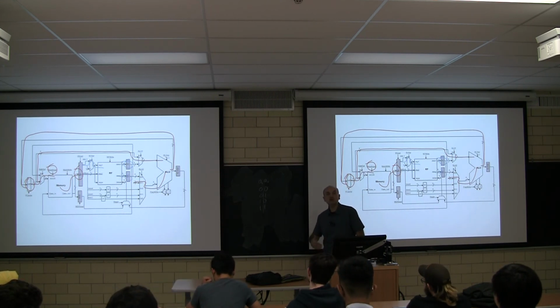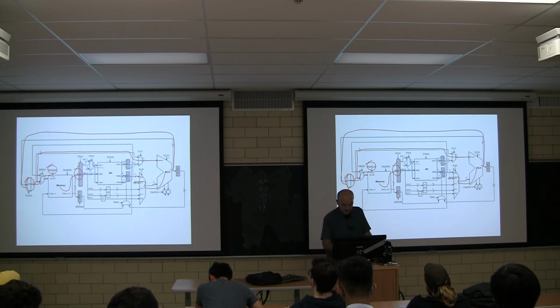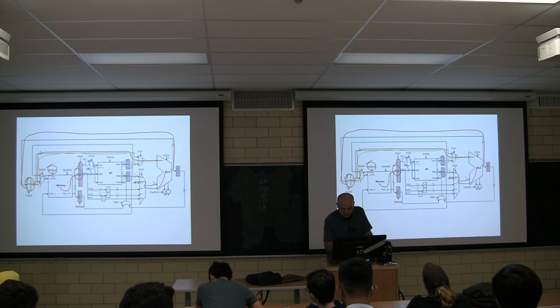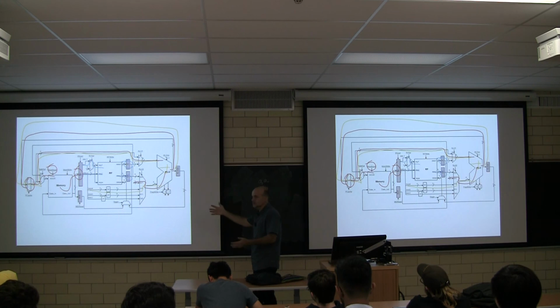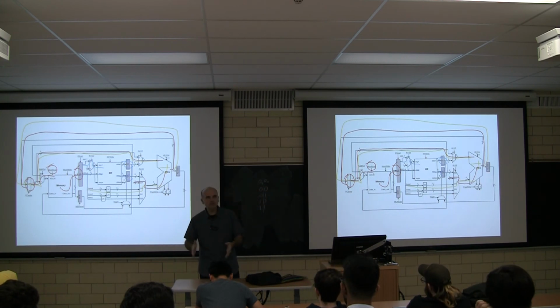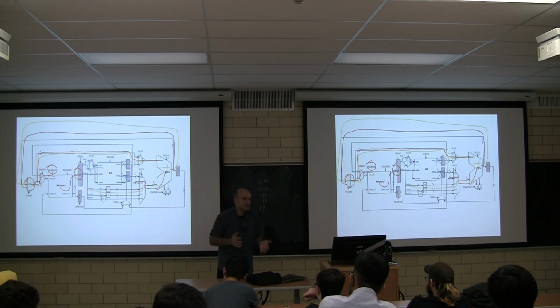Third clock cycle, now you know this is a branch. If necessary, then you take the PC again. You send it as the first operand to the ALU, and then you take the immediate 4 as the second operand, you do a plus, and you update the PC again. The net effect is, because it became PC plus 1 first clock cycle, plus PC plus sign extended third cycle, you get the branch you want. If the branch is not taken, you don't even need to do this. You can potentially even terminate in cycle 2.